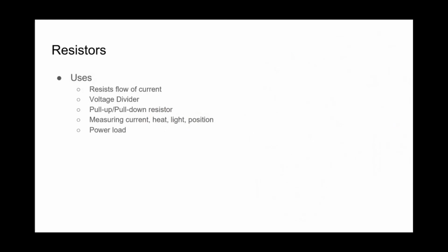Power loads. So let's say you're designing an amplifier and you don't want to blow up your really expensive speakers, or you want to test a motor driver and see if it can really handle all of the power that your motor is going to draw. Without burning out the motor or your speaker set, you would want to simulate it with a power resistor. And that's essentially what using resistors for power load is. Let's move on to useful equations.